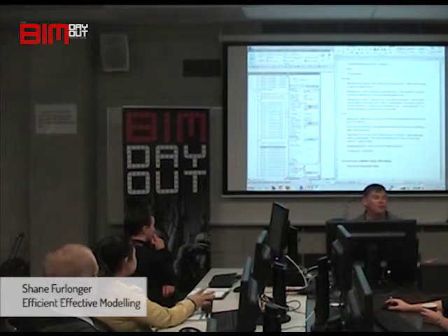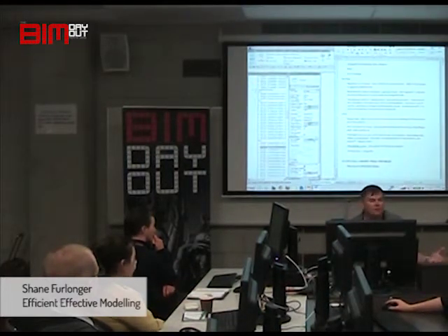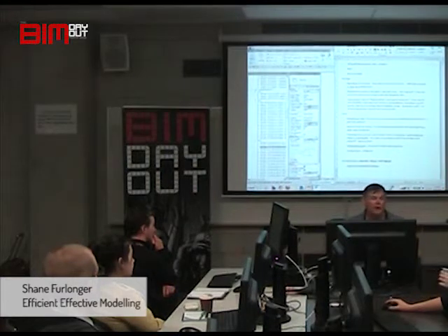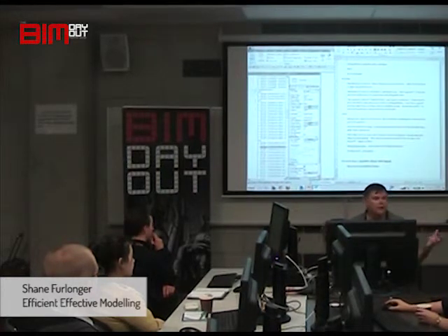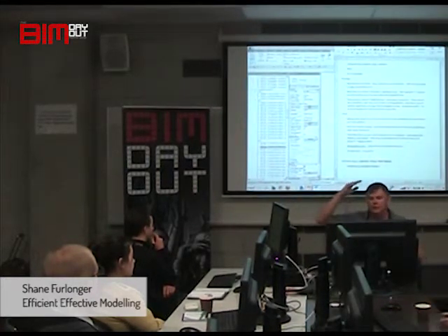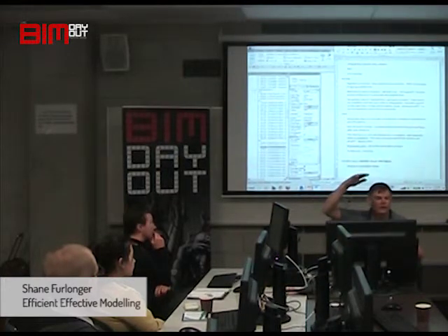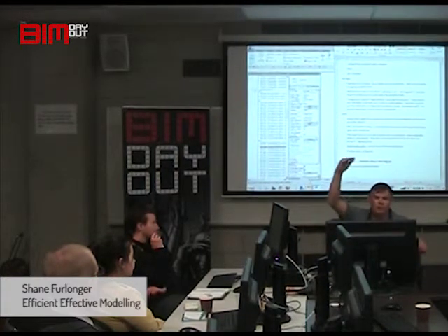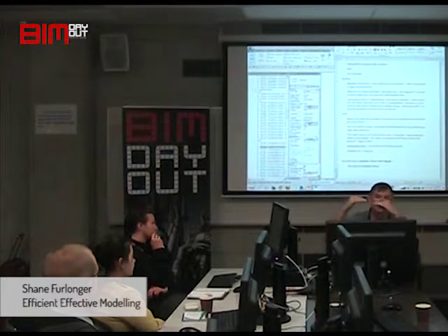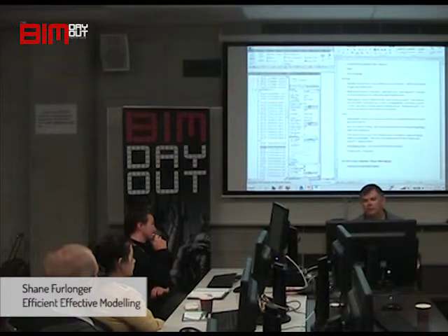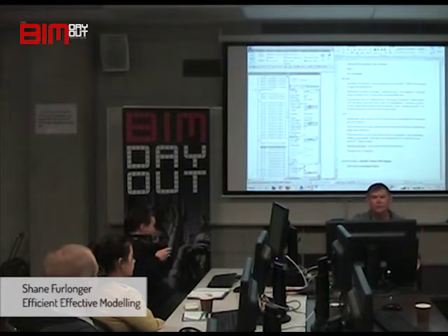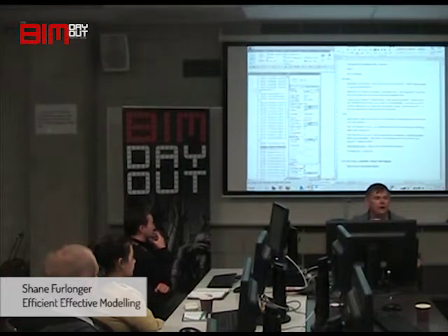Now some warnings are going to be acceptable. You'll live with them. When you're first creating your model, you may have walls overlapping height-wise, for instance. Let's say you're going level to level and you want one wall to come down slightly over the other and you're not going to worry about it straight away. But go around later and tidy it up. You can do that by just going back and reviewing your warnings and seeing these things.